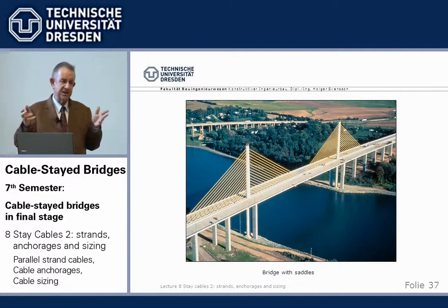An advantage can be that you save the 2 cable anchorages at the top by going through continuously. It's always cost which is behind these crazy ideas. Jean Muller did it for the first time here. The problem, of course, is you need a saddle, and the fatigue strength of the saddle was always a little bit subject to discussion, and therefore it wasn't normally used.